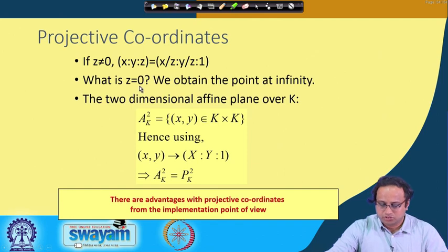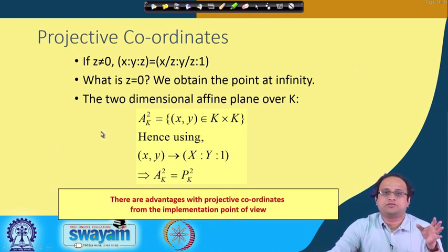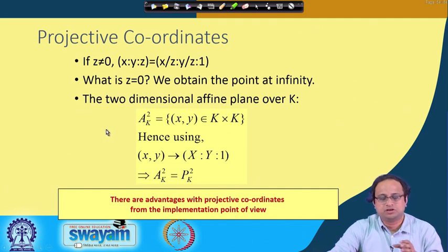Okay. So let us try to see how we can do this computation. Of course, we have to see the advantages, and only if it is advantageous, because there will be some increase in computations also when you are converting from the affine coordinates to projective coordinates. What you have to see is whether the cost that you are paying gives you benefits. Okay. So the whole idea of whether you should go into projective coordinates will depend upon your M to I ratio. That means the cost of the multiplier compared with your inversion circuit. Okay.